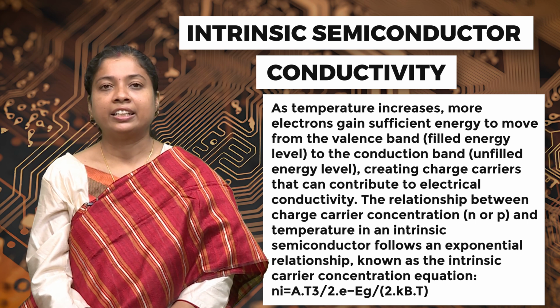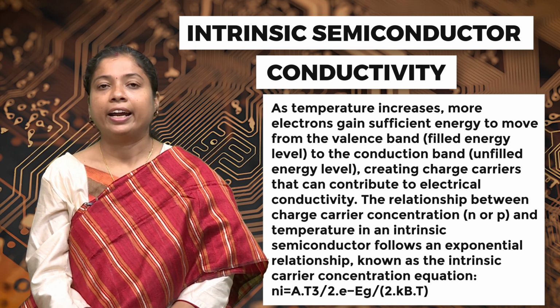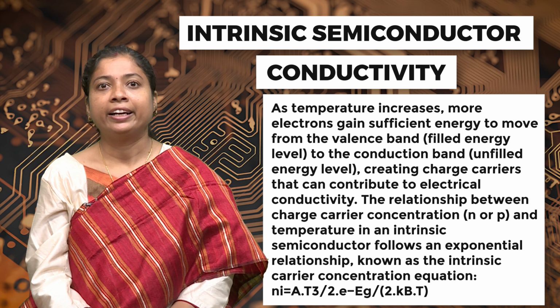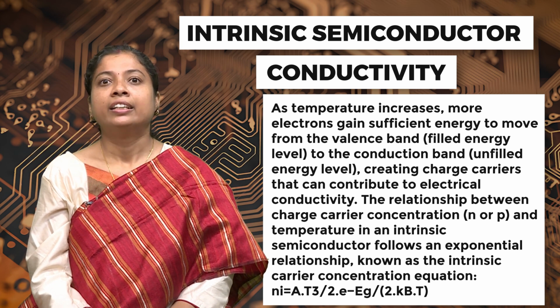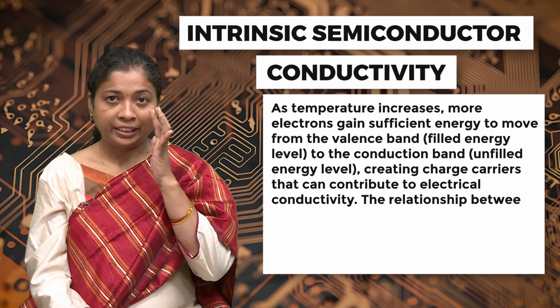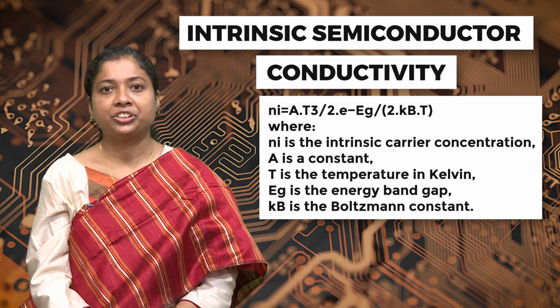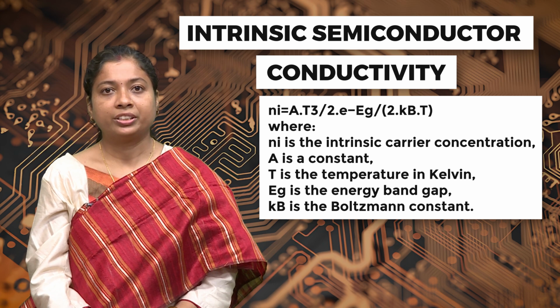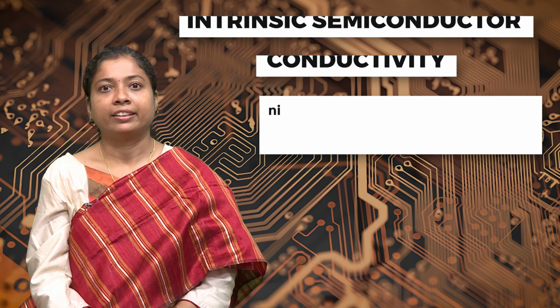That equation is presented in a mathematical form, which is Ni is equal to A T raised to the power 3/2 times e raised to the power minus Eg divided by 2 kB T, where Ni is the intrinsic carrier concentration, A is a constant, T is the temperature in Kelvin, Eg is the energy band gap, and kB is the Boltzmann constant.